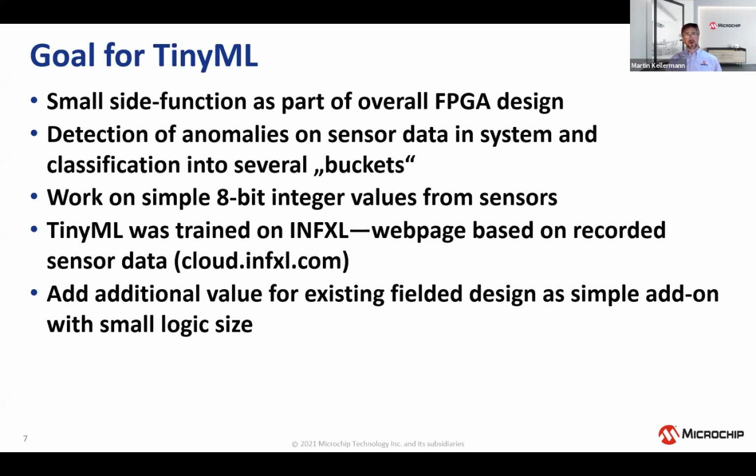What I was using on the C code is the tool called LegUp. This takes C or C++ code and converts it into something synthesizable, into HDL code. This HDL code can then be taken into a normal FPGA design and implemented just as a normal IP as you would get it from anywhere else.